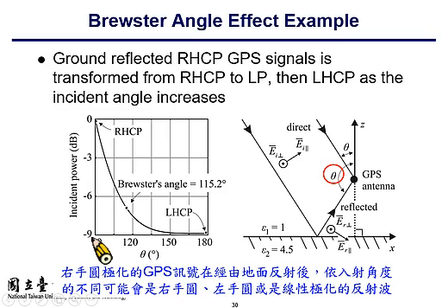If we look at theta between 90 and 180 degrees, you find that the reflection is right-hand circularly polarized for a smaller theta angle, but it becomes linearly polarized for 115 degree incidence. Because this is the Brewster angle between air and the Earth,